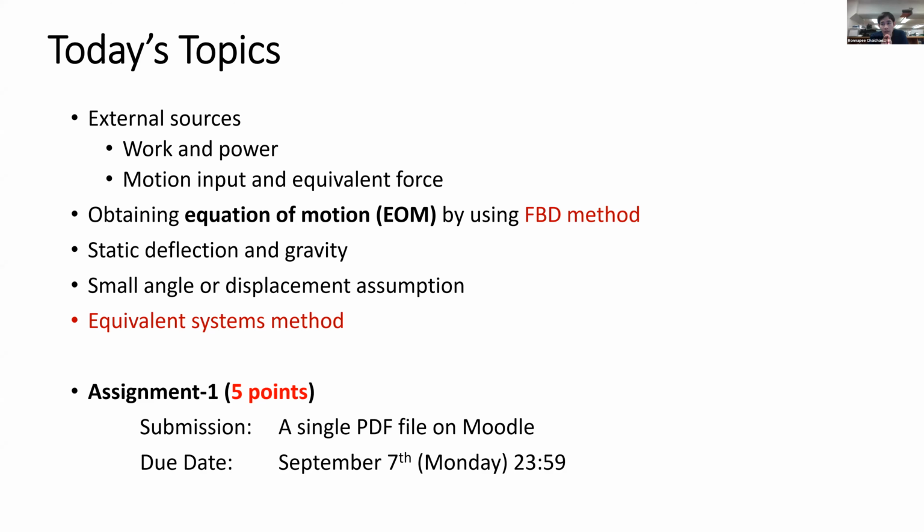Sometimes when we work with a mechanical system that has a spring as a component, we may be confused about which level should be the datum, or the reference, of the system. By knowing the relationship between gravity and static deflection, we have a better way to select the datum of the system to consider the energy or the force of the system.